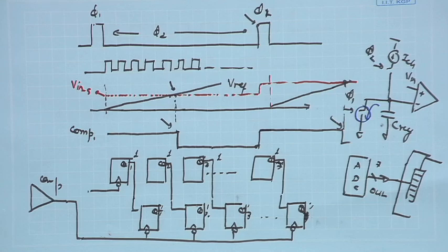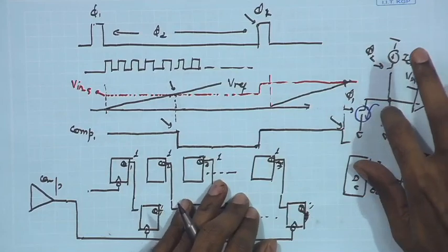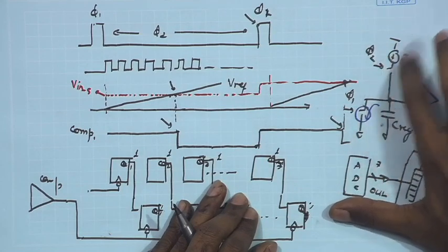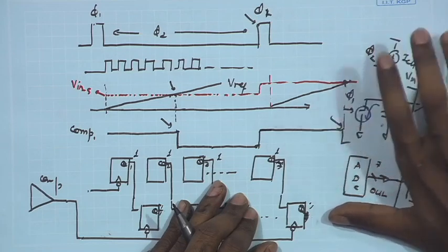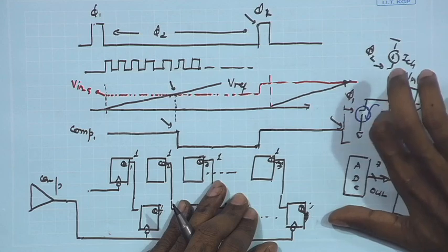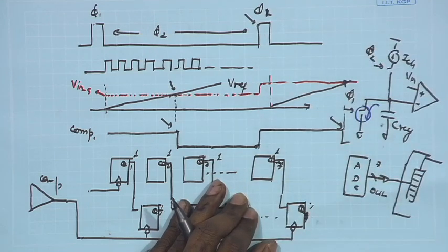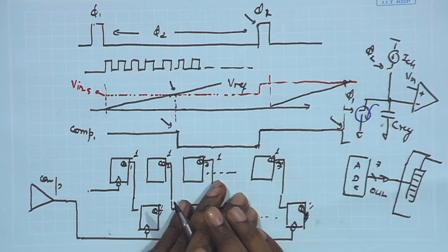So we looked at the constant current source, and we tried to keep this sufficiently large so that we are able to have a current of around 0.1 microampere. If we go for smaller capacitance, then the current required will be further lower and it will be less reliable. So that was the reason why we chose such a large capacitor of 20 picofarad.